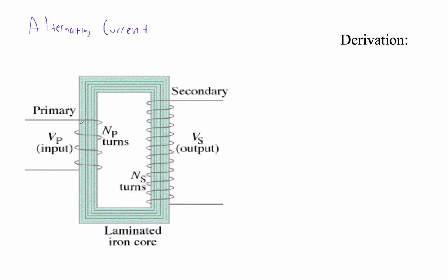But if it's constantly changing, then the primary sets up a magnetic field in this wire that first goes this way, then it goes that way, right? And that magnetic field is carried around. These things tend to be like conductors of magnetic field, right? And so ultimately, this primary changes the magnetic field in the secondary and induces a current in the secondary.